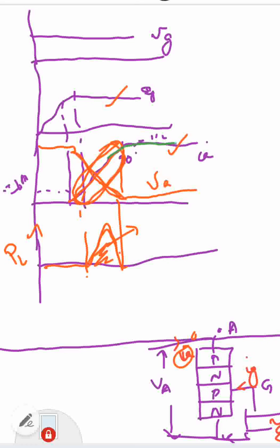Now it is in the full value, it is now flowing. Now the anode current slowly decreases and it has reached zero value. So at this instant, the anode current flowing through this device was reached to zero value, which means initially assume that it was flowing at 20 ampere, reduced to 15, 10, 8, 5, 4, 3, 2, 1 and 0.